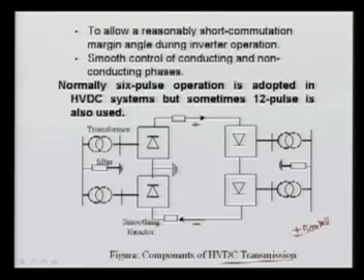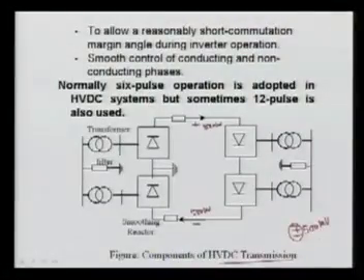It shows that this is 500 kV with respect to ground, and this is also 500 kV with the negative sign. So plus minus is shown for bipolar operation, meaning one is positive and another is negative with respect to ground. The total voltage difference between these two lines is 1000 kilovolt, and we have one line from Rihand to Dadri. It is a plus minus 500 kV line feeding 1500 megawatt power.